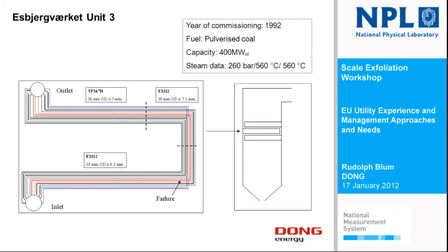And then it settles. When you drain the boiler, only those tubes ending up at the bottom of the header are exposed to all the exfoliated material. And that was it. We made an intensive effort to find and control all tubes coming out from the bottom or leading up to the bottom.